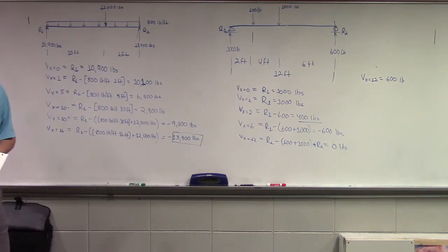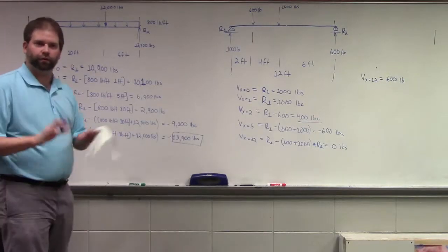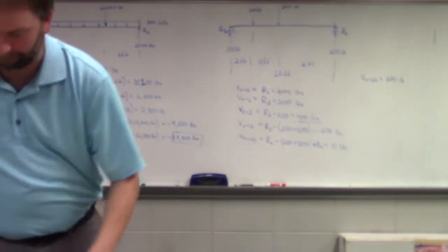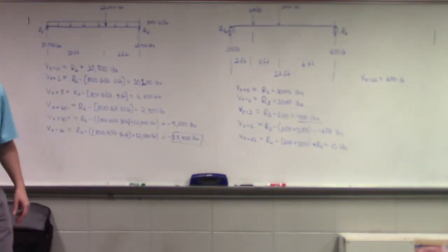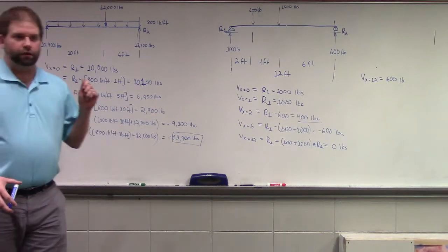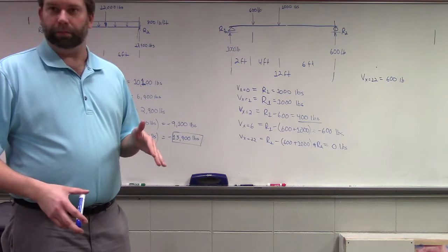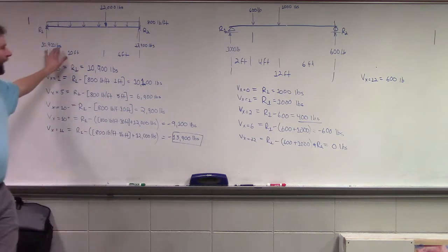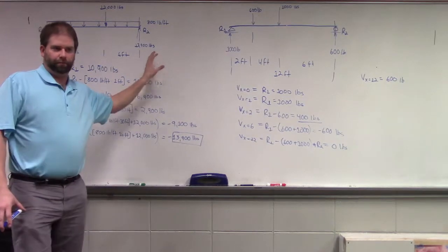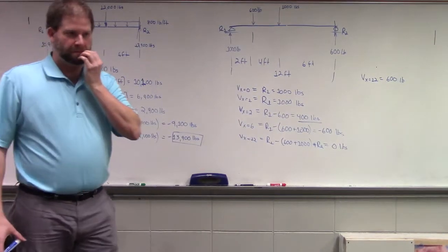You don't have to say that it's negative or positive. Since they give us the reactions, we don't have to do all the math; we know just by looking at it that 13.9 would be the maximum. You may assume that if you are given the reaction forces, the beam is in equilibrium, okay?